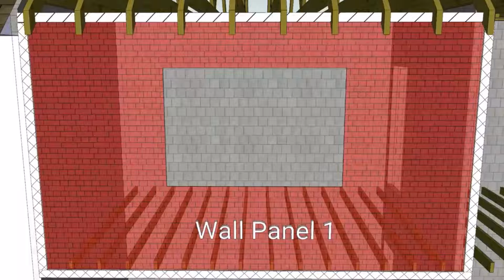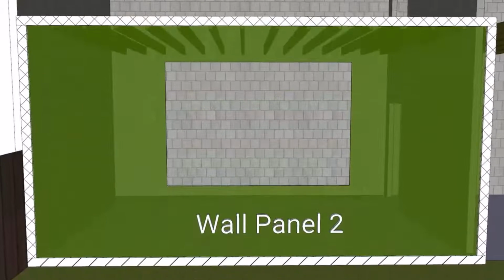Wall panel 2 on the bottom left, again, along the top there, the floor joists on the first floor allow for continuity, therefore again a fixed edge. The left hand side, a continuous fixed support due to the perpendicular party wall and continuation onto the neighbouring property. The right hand side of the panel, again, the internal return wall will allow for continuity, therefore fixed. And the bottom, damp proof membrane, which will impact the moment resistance of the wall, so we will assume a pin support here. I'll note the moment resistance can be enhanced by vertical load and properties of the DPC material.